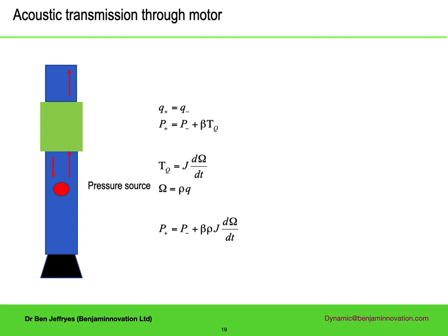It's not immediately obvious why the motor should reflect low-frequency sound. To get a reflection, there has to be some relationship between pressure drop and flow rate, and the pressure drop across a motor depends on the torque applied to it, not the flow rate. But there is a dependence when there is a lot of mass being turned by the motor.